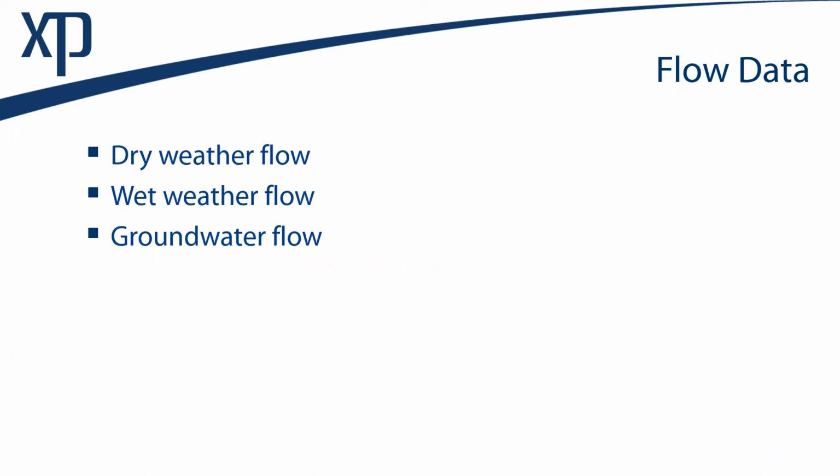Well, there are a variety of different ways. We can look at the meter data at the curb and then look at the total flow and back out how much is coming from wet weather or from groundwater. So there's a number of different techniques to try to estimate what our wet weather flows are, but ultimately we're going to have to calibrate the model based on the meter data that we have and the other flow that we're seeing in the system.